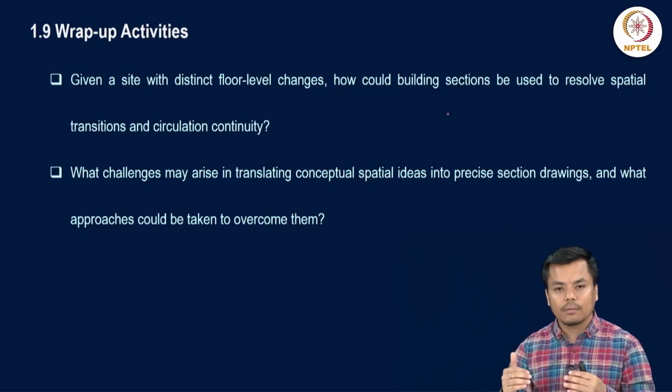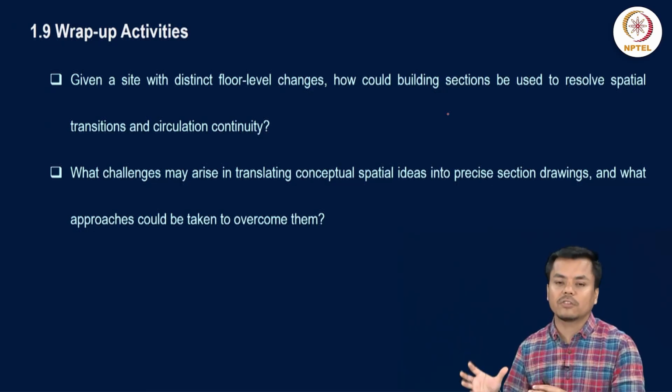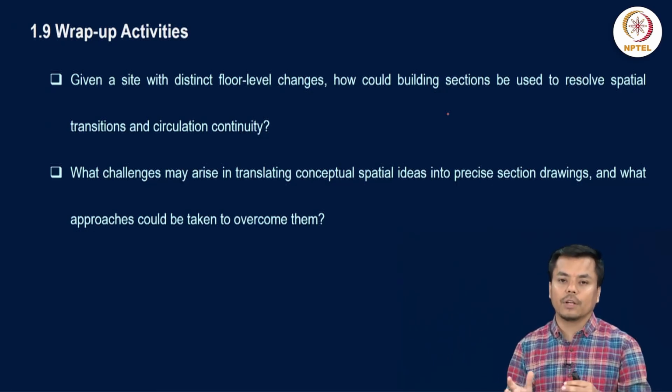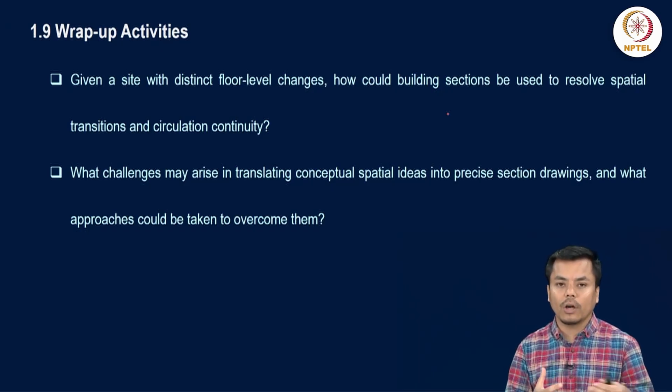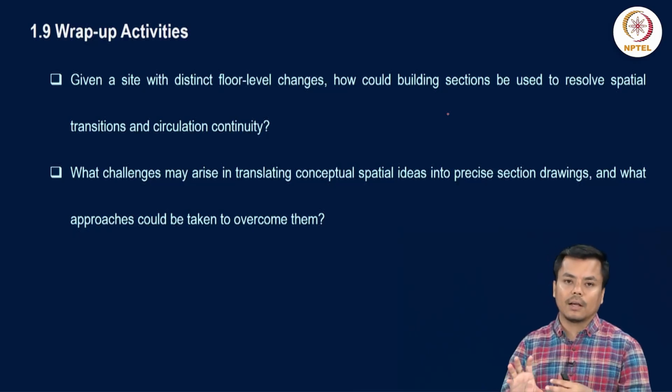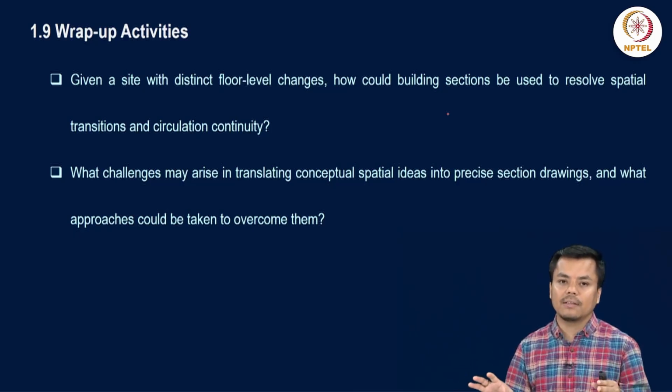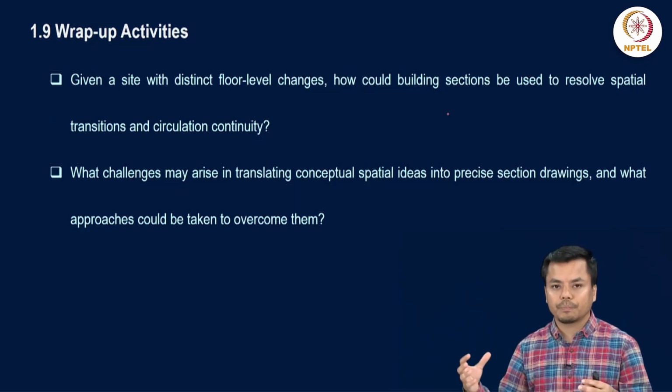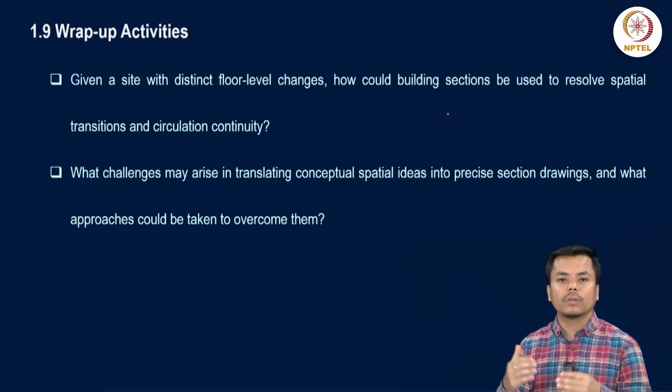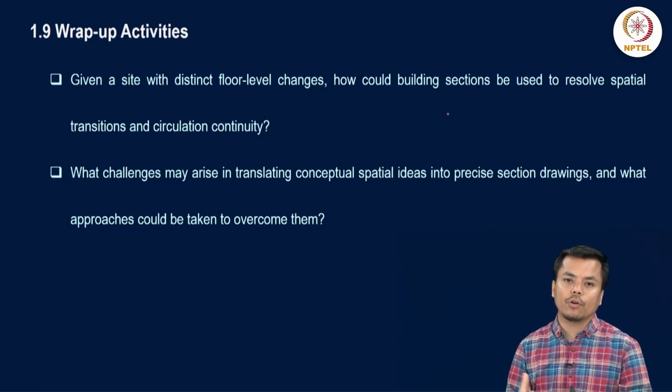So with the help of only section you could clarify all this confusion related to the change in levels in your structure, and also regarding the sunken floor, if you have introduced it in toilets or in your kitchen, so that the services can be integrated seamlessly in your design, and you did not raise the floor for your toilet or for your kitchens to include all those pipes and all those traps for the different drains that are necessary in these spaces. So that is why your section drawings are to be drawn with that much detail.